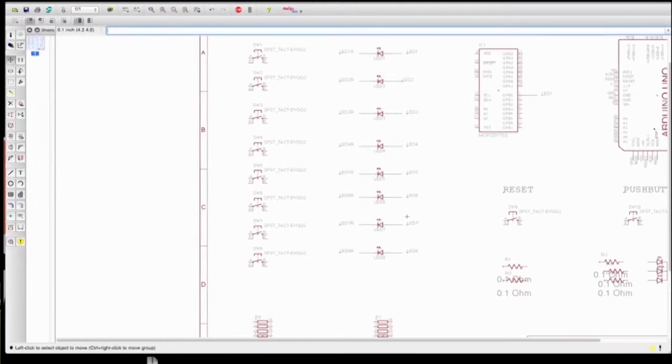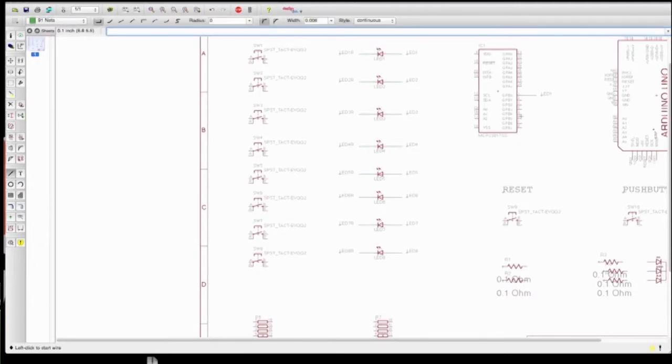Okay, so I just did these. I'm going to clean up this again. This is just me being a little crazy about the design. So I've labeled all the LEDs. Now I haven't finished over here on the 23017. So let me walk through here again. So basically I'm putting a small wire just like that. So I click, and then when I'm done where the wire is, I just double click. Double click basically says the wire ends here. If you don't double click, and you click once, it'll keep running like this. See how it's running like that? Or you can escape and it'll quit. So basically I'm just putting in a small wire just like this.